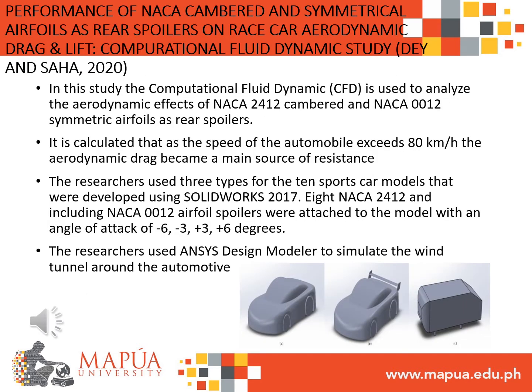Performance of NACA-cambered and symmetrical airfoils as rear spoilers on race car aerodynamic drag and lift: a computational fluid dynamics study. In this study, computational fluid dynamics is used to analyze the aerodynamic effects of NACA 2412 cambered and NACA 0012 symmetric airfoils as rear spoilers. It is calculated that when the speed of the automobile exceeds 80 km per hour, the aerodynamic drag becomes a main source of resistance.